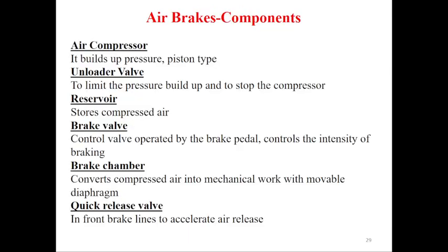Next are the air brake components. First is the air compressor, piston type, to build up the pressure. Second is the unloader valve, third is to limit the pressure build up and stop the compressor. The reservoir stores the compressed air. The brake valve is the control valve operated by the brake pedal, which controls the intensity of the braking.